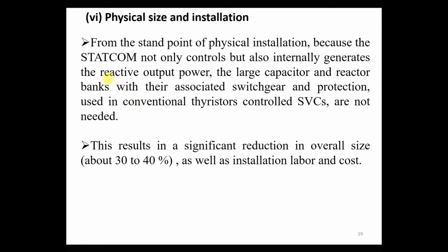So the size of the STATCOM is less, because there is no requirement of large capacitors and reactors, with the associated switchgear and protection that we require in the thyristor controlled SVC.